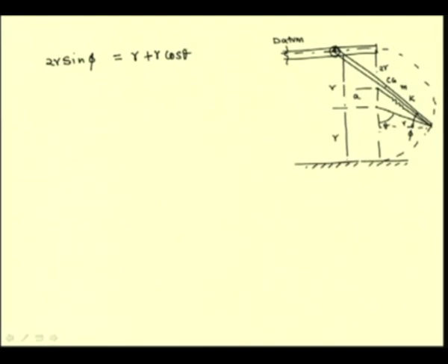because this distance, which is r cos phi, is equal to r plus this distance, which is equal to r times cos theta, and so the CG is located at minus r plus r cos theta divided by 2, half of this distance, because this is the datum, so this is in the negative direction.